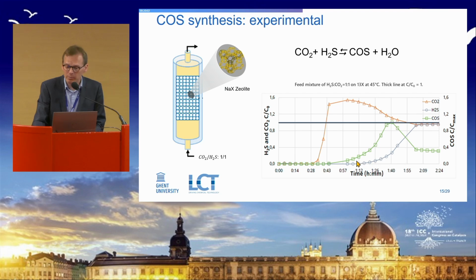Then, when the bed is gradually getting saturated with H2S and water, we see in the first instance H2S also coming out. And if we would run it for an even longer time, we would also see water coming out of the system.